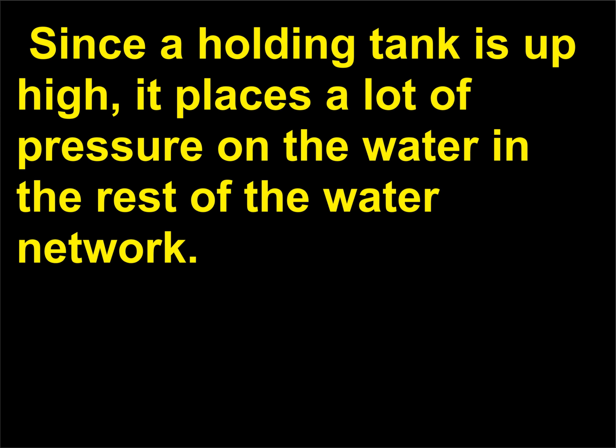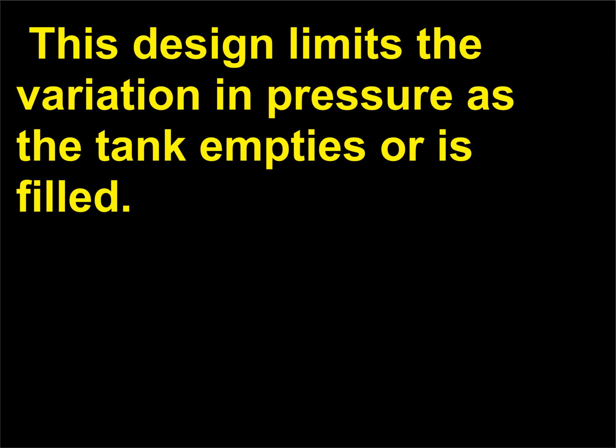The tank should be as large across as possible so that for the same amount of water the vertical dimension of the tank can be as small as practicable. This design limits the variation in pressure as the tank empties or is filled.